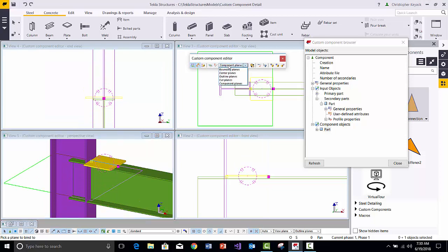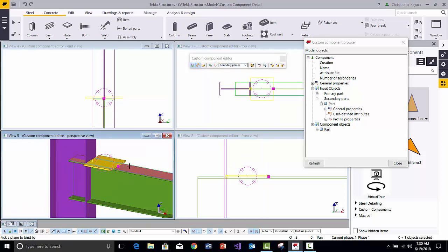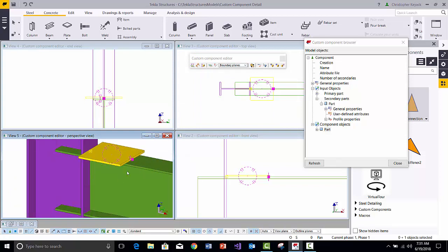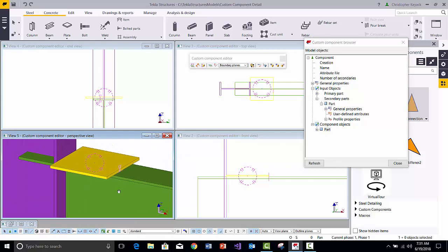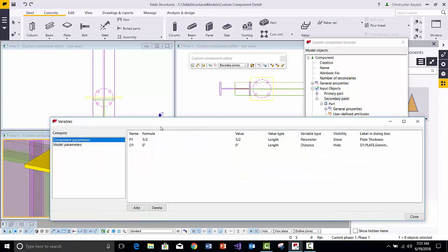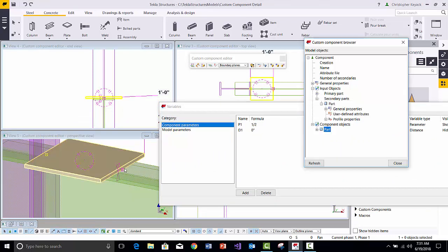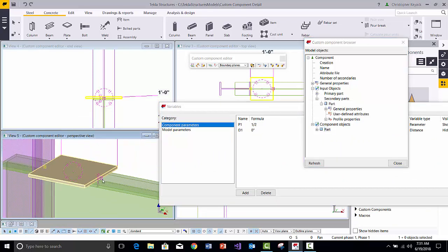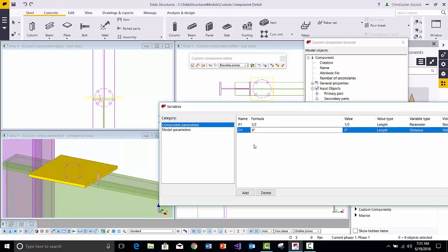Now in this case here, all we really need is boundary planes. So we're going to bind ourselves here to this top flange, and when I click on it, it creates a distance in the model. So there's this little dimension that basically appears here. And right now you can see that the dimension actually zeroes out or touches each other because, again, the picking point here of this plate is lined up directly with the top flange. Now, this is really great. If I can basically bind or glue the surfaces and the points of these plates to the beam flange and get 0 values, this is good.